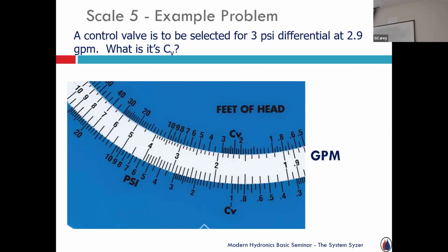And all you do is you read back and you find, what's the number right here? So I got 1, 1.1, 2, 3, 4, 5, 6, 7. I would look for a valve manufacturer that states their CV is 1.7. So at 1.7, that says, hey, when I flow 1.7 gallons a minute through that valve, it creates that 1 pound pressure drop. That becomes my CV rating. And that's a standard in the industry: whatever the flow rate is to create 1 pound pressure drop.